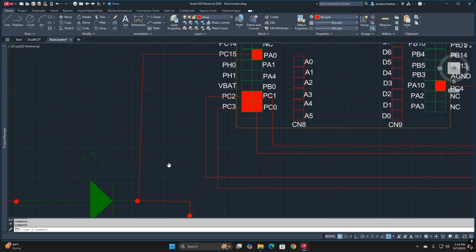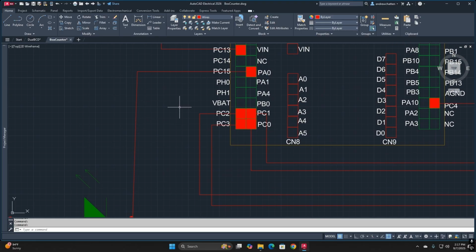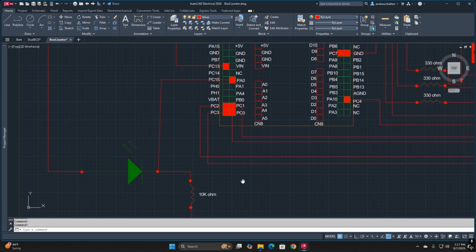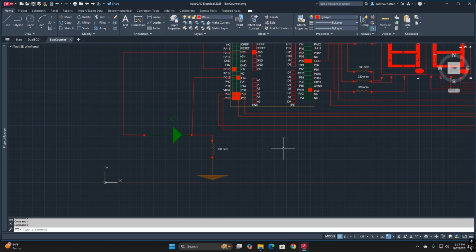Okay, so don't feed it in the switch directly. You sort of feed it in the digital in indirectly, and so that is a good way to go. I think I showed on how the photo transistor worked. So it's going to work as the box crosses the laser beam. It's going to count.